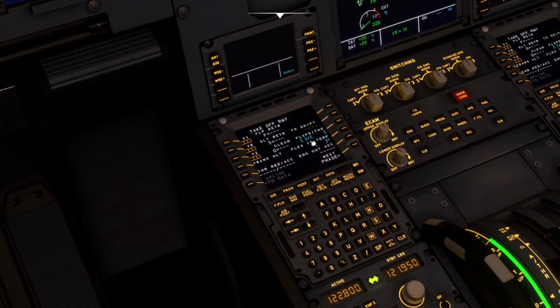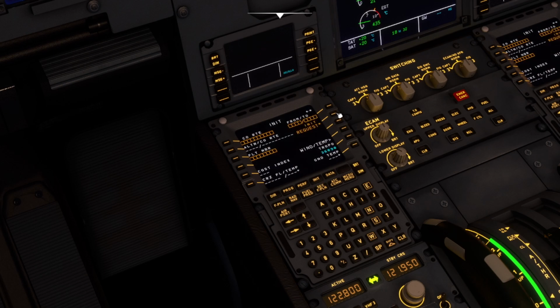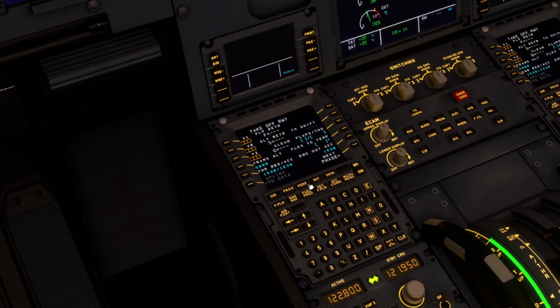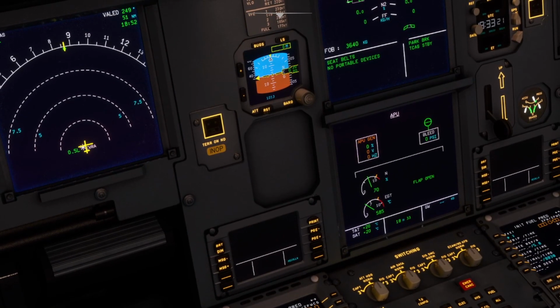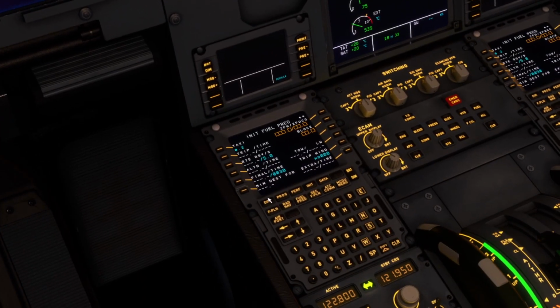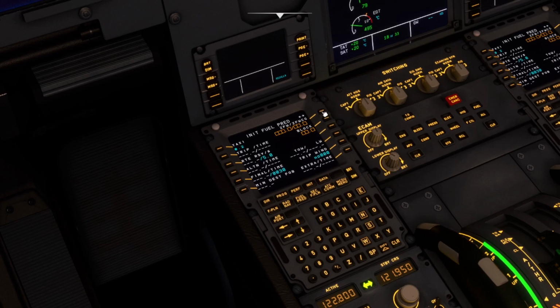And let's move forward to the INIT page and press that request button, and it's automatically synchronized with SimBrief and all that info that we need is in here. And let's put in some info about the takeoff performance. So we need flaps 2 and trim will be 1.0. Flex 45 degrees. And before we confirm the takeoff speeds, we need to write the info about the fuel.